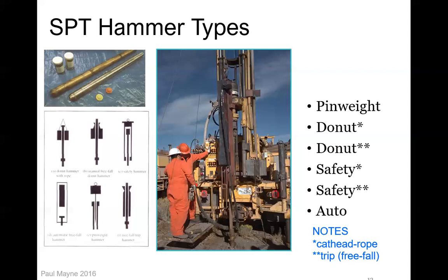Like 61 feet. Okay, that's clearly going from a red clay to a blue sand or whatever. But in Florida, when we're using the wash method, you can't do that, because what's coming up is driller's mud and it's all nasty gray stuff. So you can't discern when the soil layers actually change. We're going based strictly on the SPT sampler. So we're taking those point shots and just interpolating, or each engineer has his own technique to determine what the soil layers actually are.